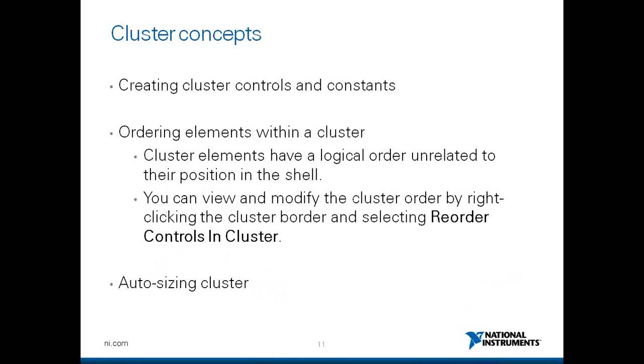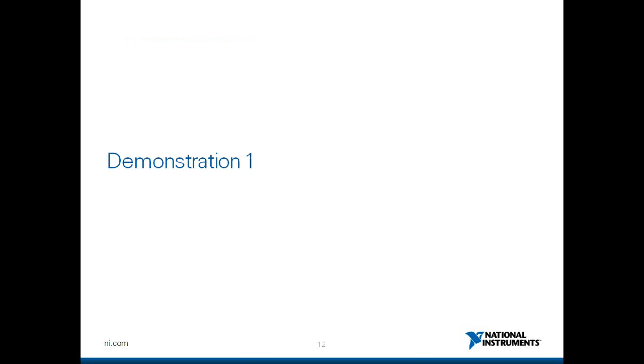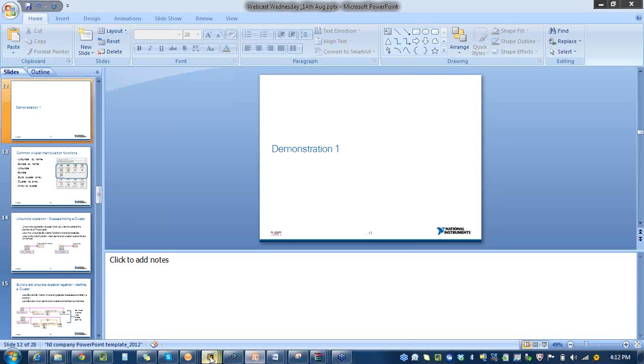So some very basic concepts in using clusters. We will go on to see all of this in LabVIEW. First on how to create cluster controls and constants. And then we're going to learn what ordering of clusters means, what ordering of elements within a cluster actually means. And we're going to learn what auto sizing in cluster means. So let's go on to LabVIEW so I can demonstrate all of this for you.